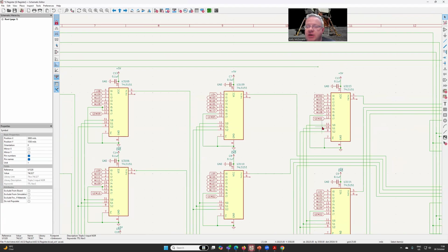The other thing I realized I had forgotten when I was designing it last time around is the scenario where the G register is our memory buffer. So it's also buffering memory that is written to our erasable memory, but it also contains the contents of either our fixed or erasable memory that we're bringing back in. So we need a scenario for, and I'm just calling these GEM, our G memory bus, in order to bring the data in from either fixed or erasable memory. That covers off 7 different potential scenarios, so we use 7 of the inputs in our selector to pick the appropriate output and then use that to write into our G register.